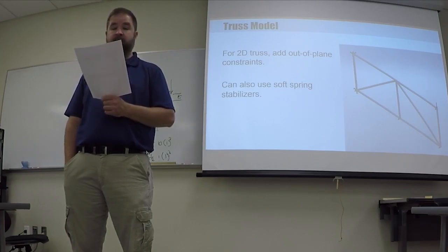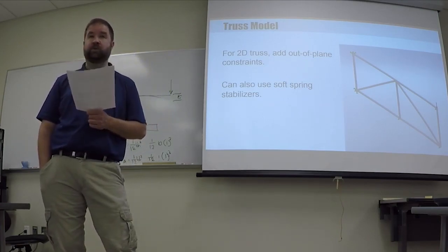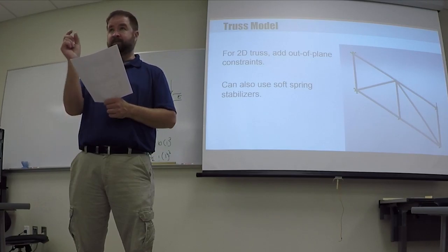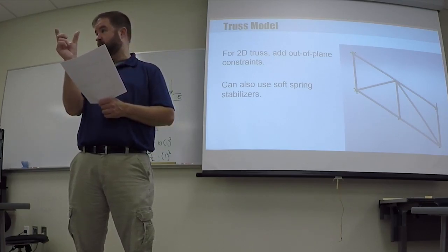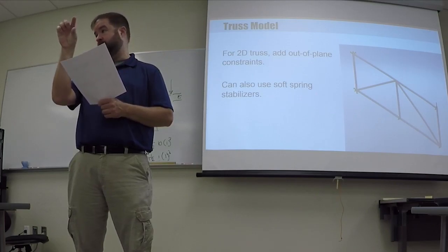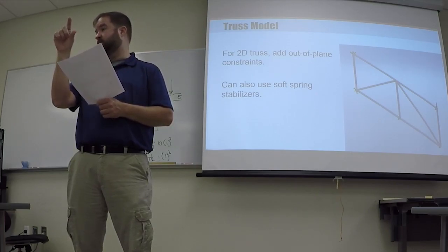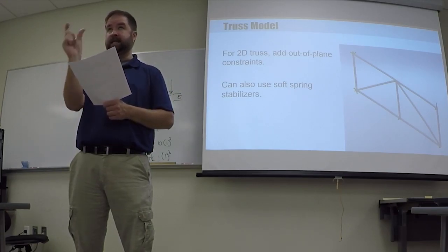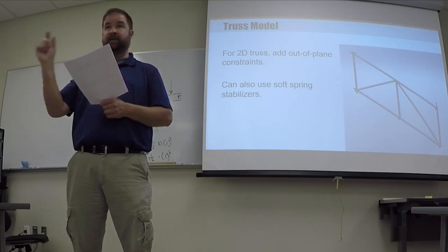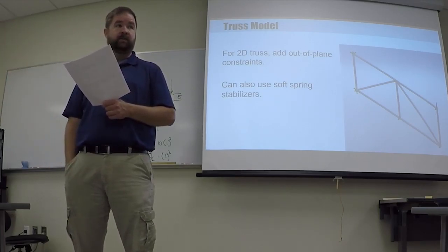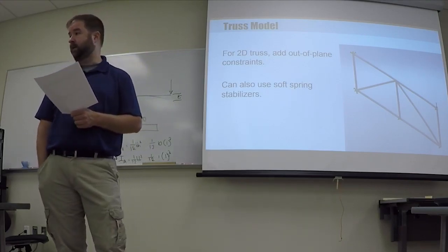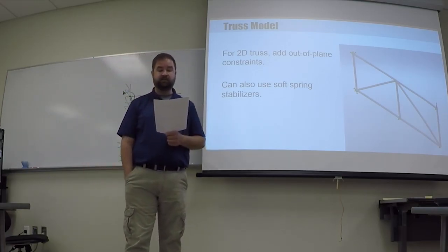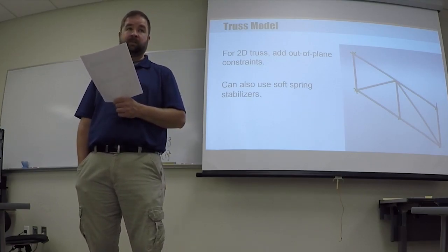Now there's a note there, that in SolidWorks the beam cannot be shorter than it is wide. So as we get down to the 8 elements one, you're going to have to tweak the lengths of the pieces a little bit so that it doesn't end up shorter than it is wide, because SolidWorks will not be able to figure that out for you. So what that means is they can't be 8 equally spaced pieces. You're going to have them with different lengths to get those 8 in there. However you want to figure that out is fine. But we just need to have 8 elements. We're using beam elements, beam type elements.